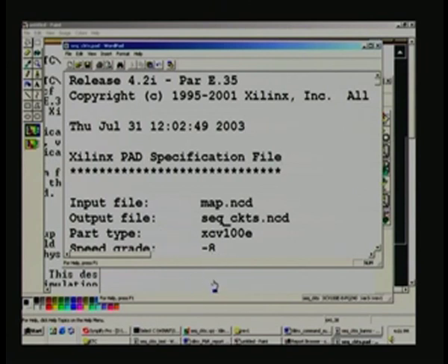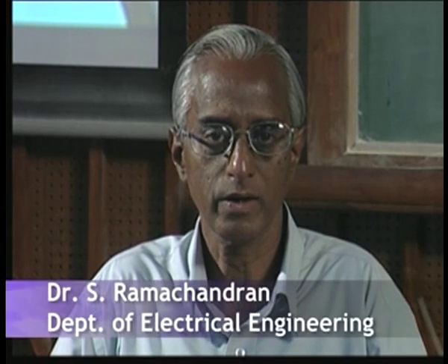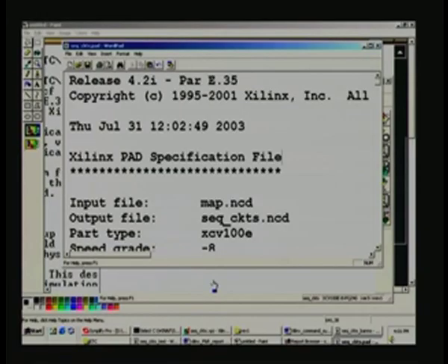You have a question? You said the level is TTL compatible, isn't it? Yes. Can we have other compatible levels also? MOS. In fact, these FPGAs are basically MOS based version. So they have what are called TTL tolerant voltages. The chip itself may be working at 1.5 volts or 3.3 volts and so on. So no matter what the supply voltage is, they will have compatible IO, so that any other TTL or any other device, CMOS or MOS, can be connected.